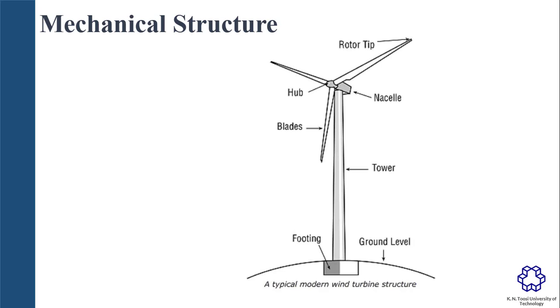Here, you can see a simple sketch of a wind turbine. A wind turbine has four major structural components. Rotor blades are the most important parts in a wind turbine. The majority of horizontal axis wind turbines have three blades. Having fewer blades reduces drag, but two-bladed turbines wobble when they face the wind. So, due to some stability challenges, three-bladed turbines are more desirable. A blade is simply an airfoil mounted on the hub, which rotates the low-speed shaft in the nacelle.